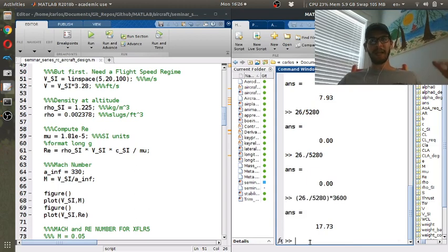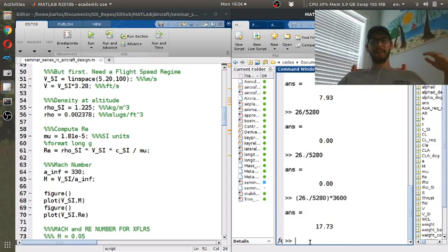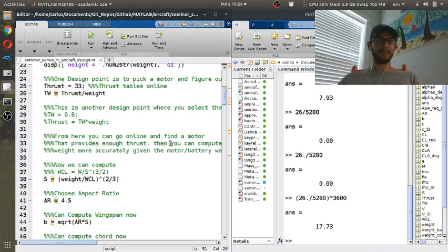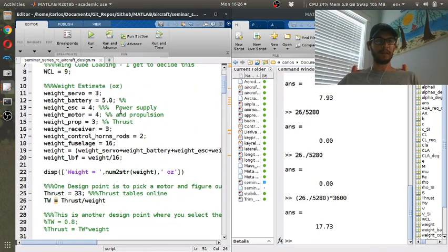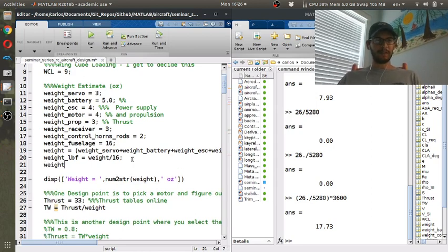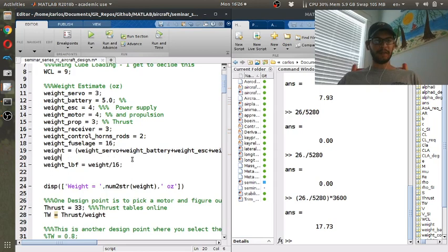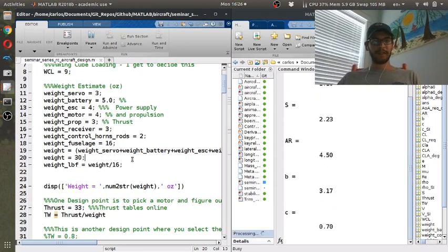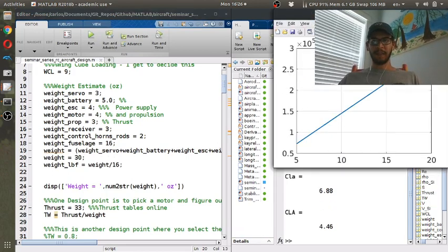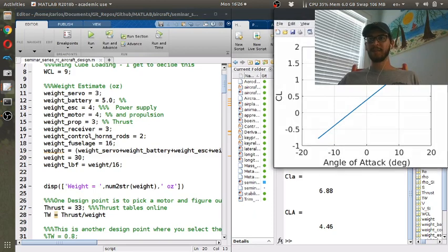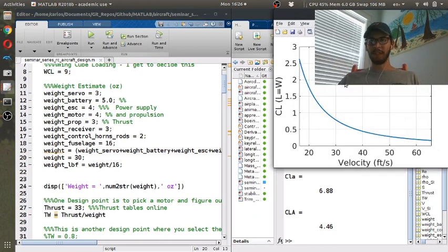So yeah, I'm going to have to put landing gear on this thing and really cook it down the runway. Or what I'm hoping is that my weight is just completely wrong. So I did the wing cube loading of 9, and I got a weight of 40 ounces. But imagine if I did 30. Let's see how that changes my vehicle. Now, this is what's nice about this program, I can do a redesign.